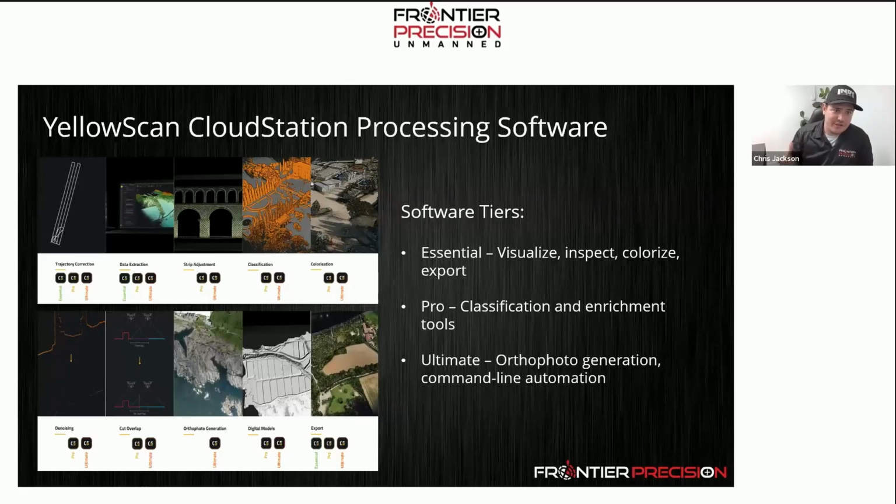We're actually doing the data extraction, so generating our point cloud, performing strip adjustments. A lot of times if you're doing multiple flight lines, there can be some variance in how your points line up. And we want to have the flattest plane that we can have, the more accurate your data is. If there's thickness in your point cloud, that likely means that there's error tolerance there. So the thinner your point cloud can be, the more accurate it is. And that's a tool that just helps correct any of those variances.